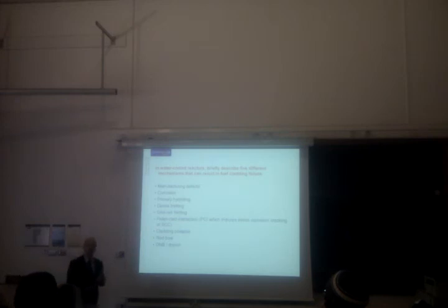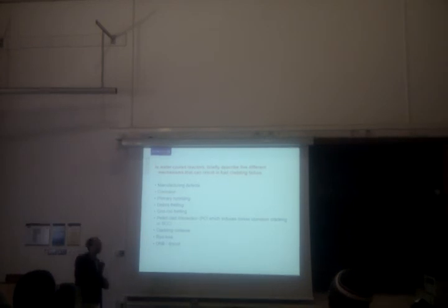That's fine if you take account of that at the design stage, but if you don't, then you can find that the fuel rod has actually contacted the top of the bottom nozzle and the underneath of the top nozzle, and continues to grow. It runs out of space, and it bows like that. You get two adjacent rods both bowing, then they can touch.